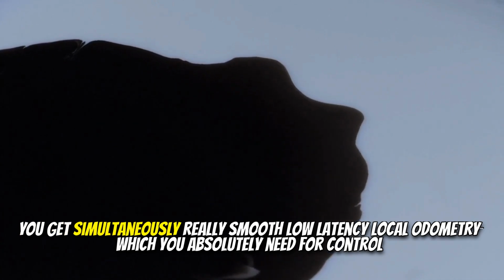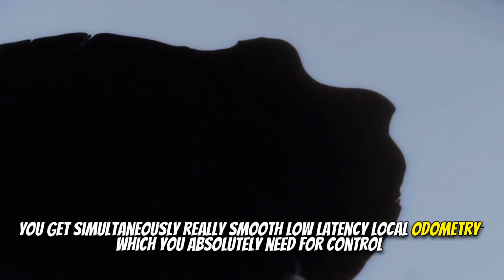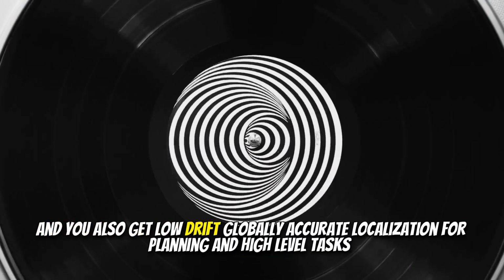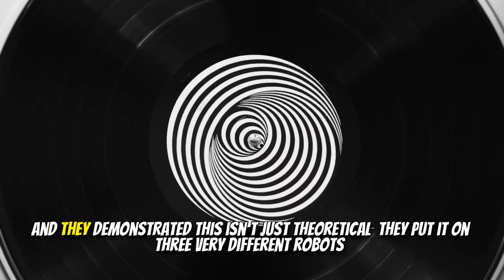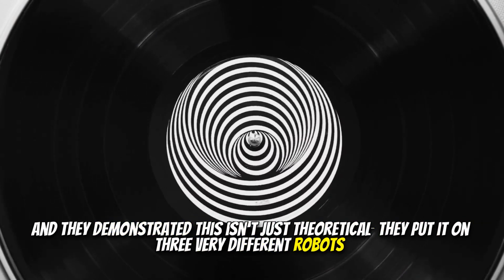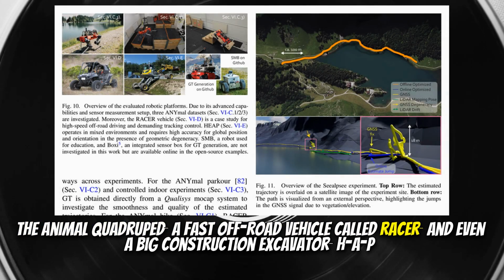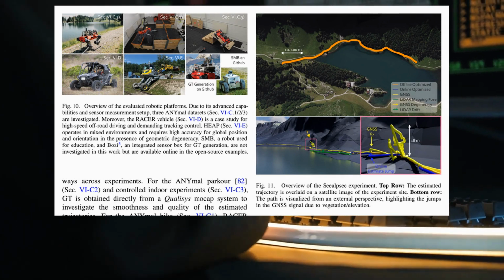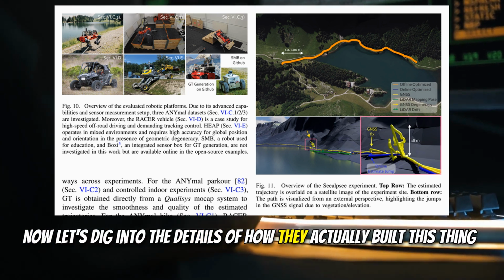You get simultaneously really smooth, low-latency local odometry, which you absolutely need for control. And you also get low drift, globally accurate localization for planning and high-level tasks. And they demonstrated this isn't just theoretical. They deployed it on 3 very different robots. The ANYmal quadruped, a fast off-road vehicle called Racer, and even a big construction excavator, HAP. Wow, okay. That's a solid range. So that's the high-level pitch. Yeah. Now let's dig into the details of how they actually built this thing.